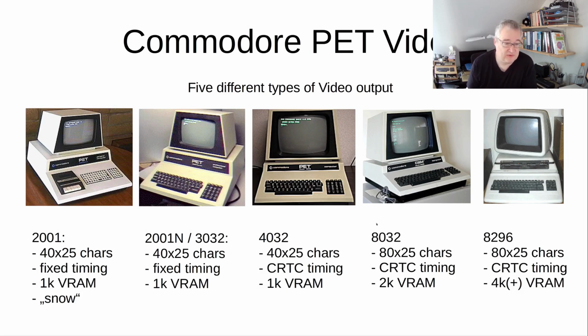So the same board, 2 options, very nice for Commodore, saving some costs. They introduced the so-called CRTC, which is the 6845 or 6545 CRTC chip that is also used in a number of other video cards, for example from the PC scene and other home computers of that time. It's a very flexible chip, but we'll talk about that in a follow-up episode.